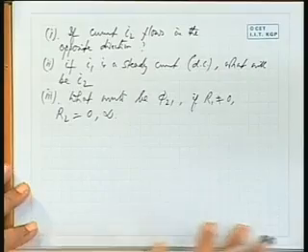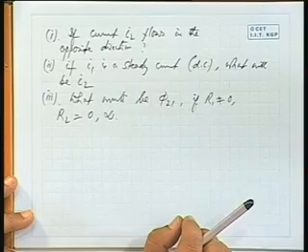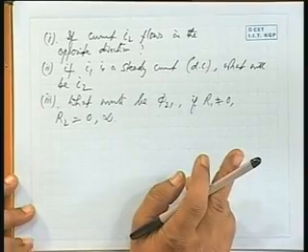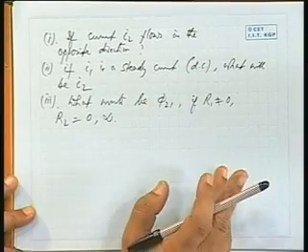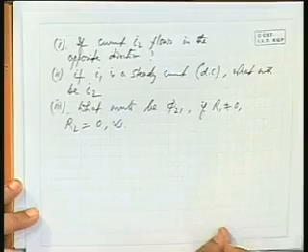So, this is a very interesting situation. For example, when you apply a sudden change in the voltage, say an impulse or pulse voltage, in a pulse transformer you get sudden changes. When the voltage does not change, there is no output on the secondary side. Whenever there is a change, there is an output on the secondary side. So, this principle is used in a pulse transformer. Okay, thank you very much. We will continue with this in the next class.